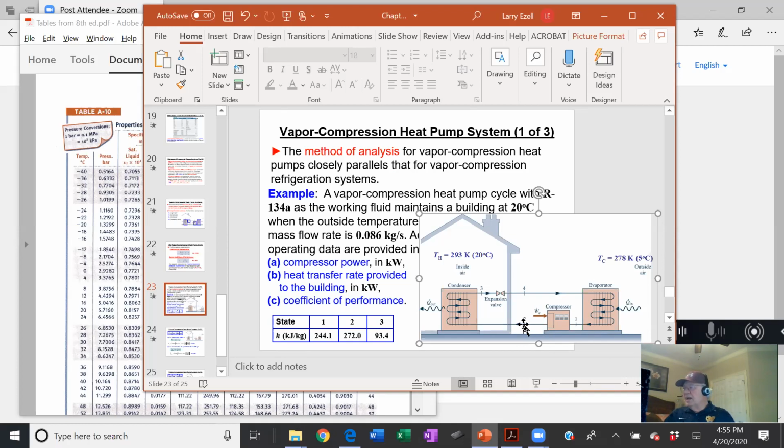Now we've got a hot, high pressure refrigerant that we run through the condenser coil that's this time inside the area you're trying to heat. So now you've got nice hot air to heat your inside. And heat pumps are really efficient devices.